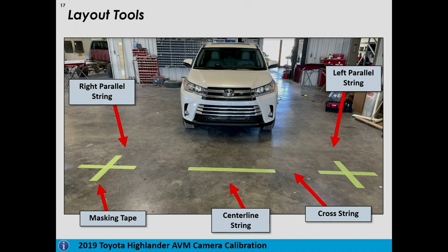Now, in relationship to why do we need to establish such a perfect center line to the vehicle? In this instance here, we've got a picture of what it looks like to do the calibrating of one of the 360 cameras. All of these images, generally like 4 cameras, we have to mesh so it looks like a 360 bird's eye view. They're not actually that, they're a fisheye lens to each one.